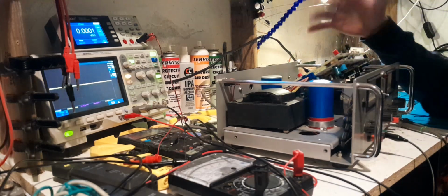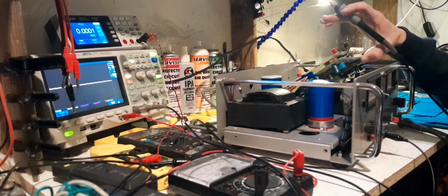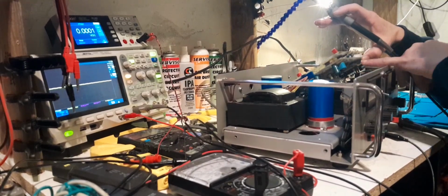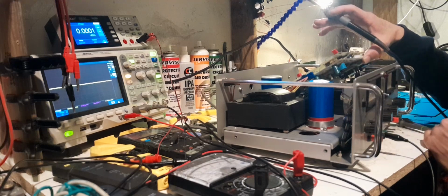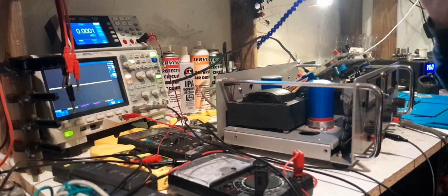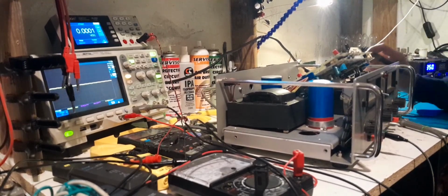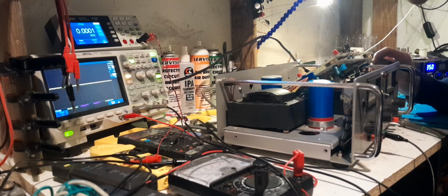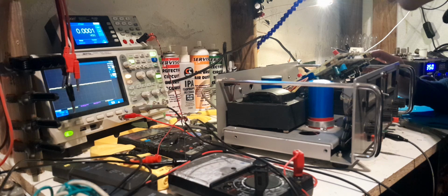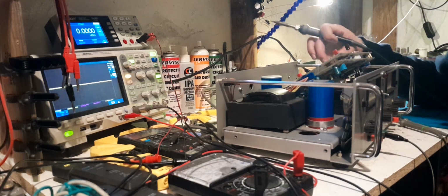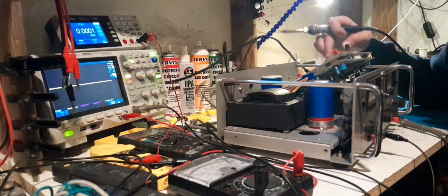Well, now we know I guess that's how the constant current circuitry is working too, and we already know which op amp and reference it is. Actually, we don't know that. That's actually a freaking good point. I have not considered that, because on the top board there's only one op amp, and that op amp powers the panel meter. So maybe the constant current reference is just directly on one input of the first op amp that looks at the constant current sense resistor. I don't know.